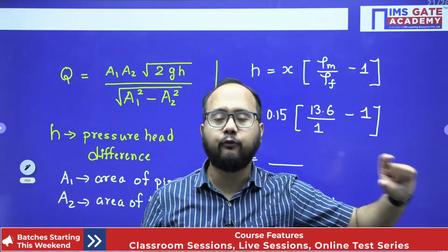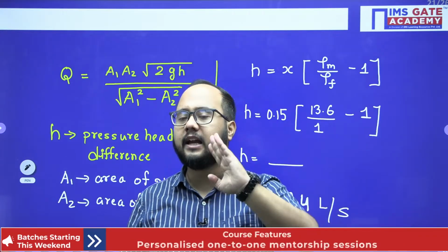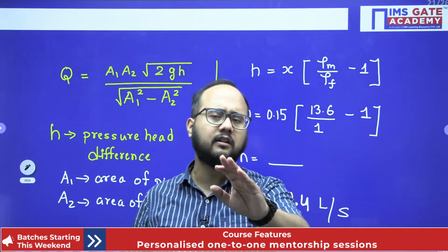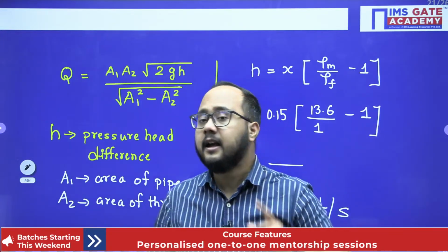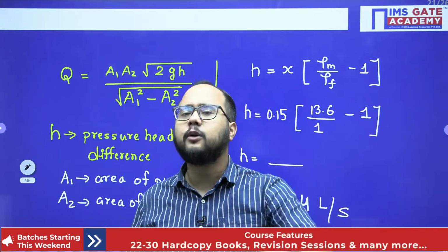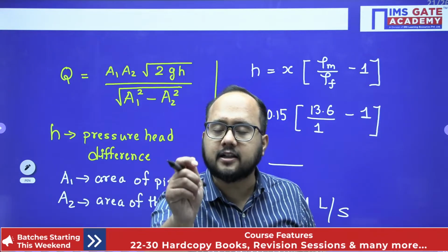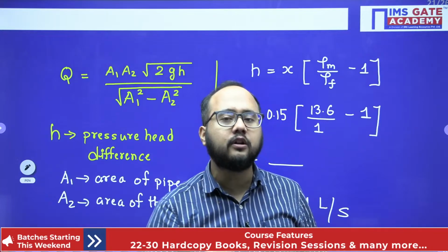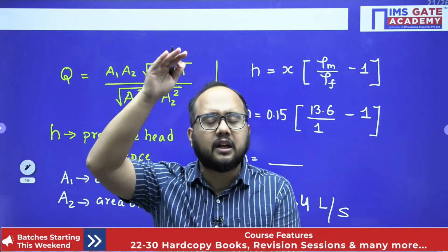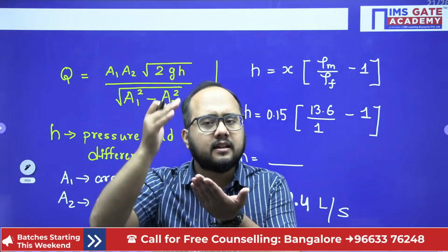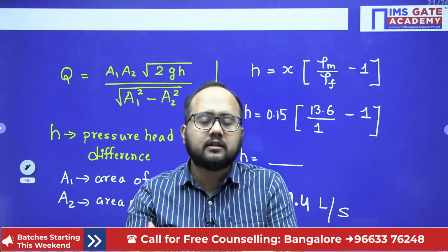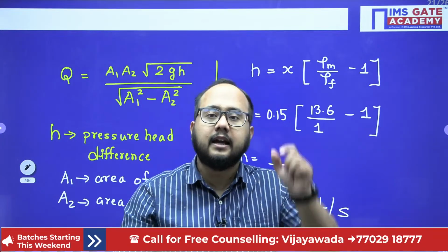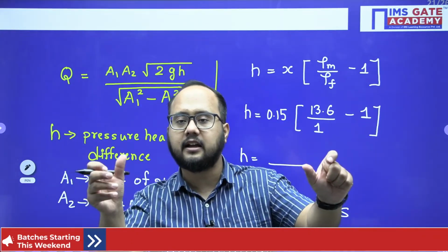In the pipe flow, if you simply have the Pitot tube, you cannot calculate the velocity of fluid flow or the kinetic head, because from the Pitot tube, what are you getting? Only the stagnation head. From the Pitot tube, what is the output you are getting? Whatever height is there, what does that height actually represent? Stagnation head. So what will I do with the stagnation head if I don't have any information regarding the static pressure head and the kinetic head?